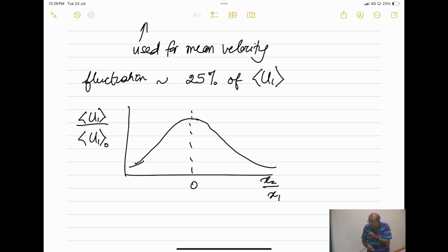And that is, as you will realize, the biggest challenge which we get in turbulent flows. Even if we assume Navier-Stokes equations will give us the solution, if it's a turbulent flow, then you have to go to scales which are very small, which means your domain has to be very small and time domain has to be small.